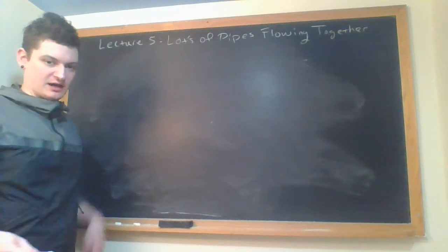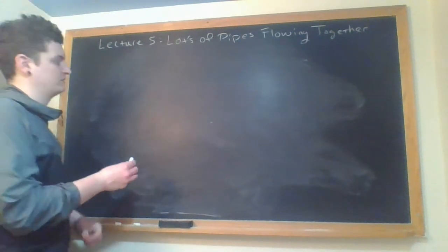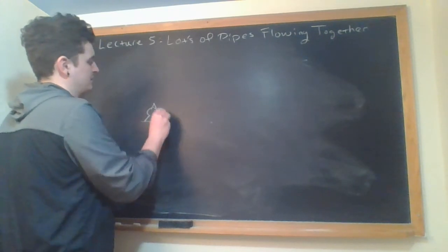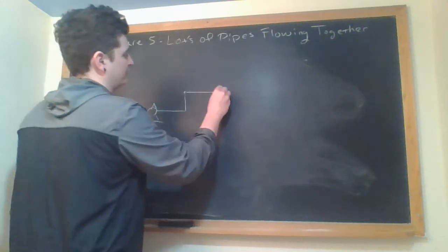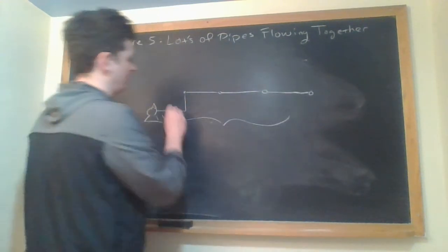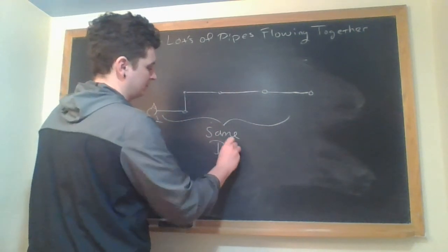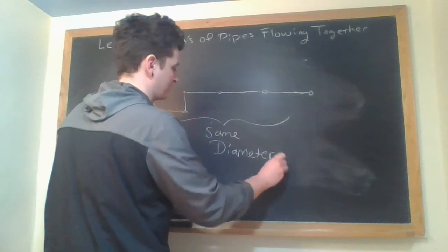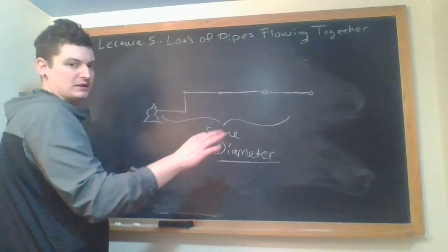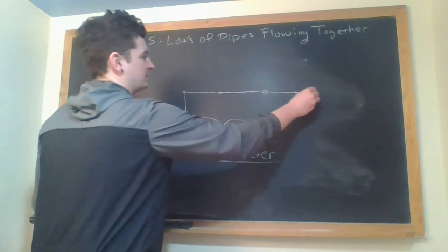So everything we've done until now has always focused on a single straight pipe, just one pipe system. So we have tools that allow us to solve problems where we have a pipe, where we have a pump, and we have just one line where all the sections technically would have to be the same diameter. They could have components in them, but if you have the same diameter throughout each component, we have all the tools to calculate head losses in terms of